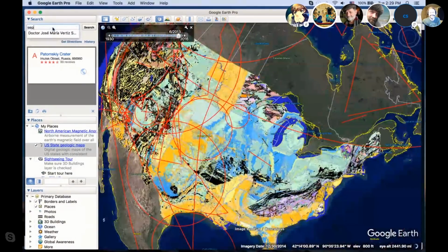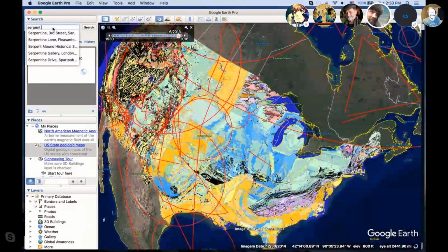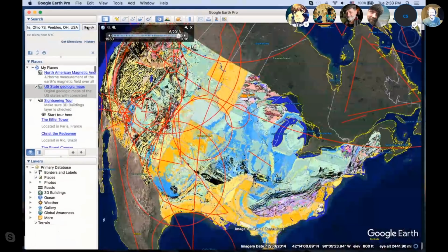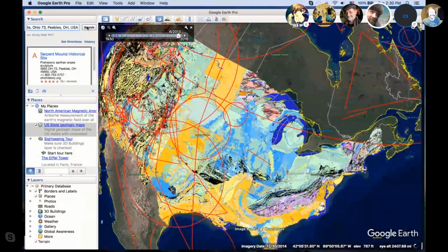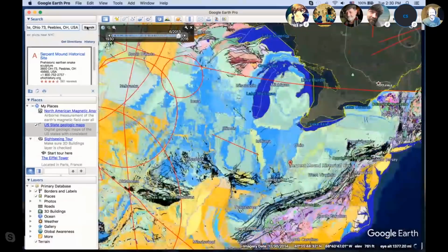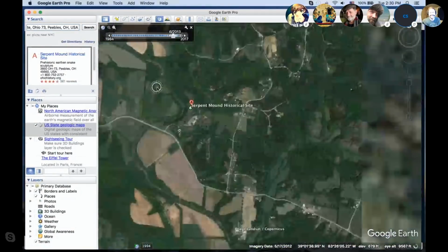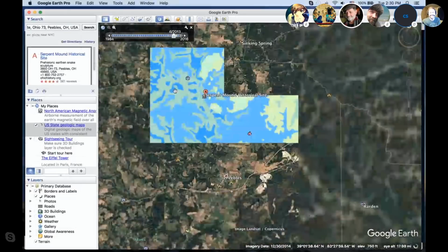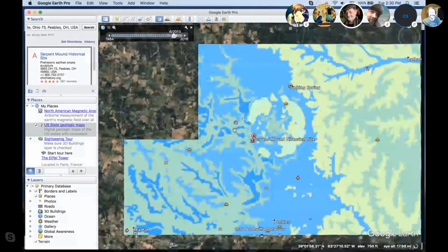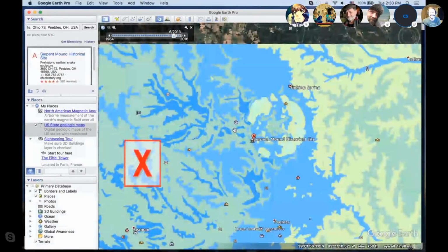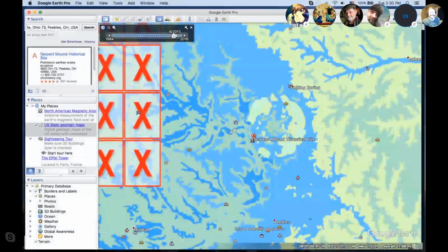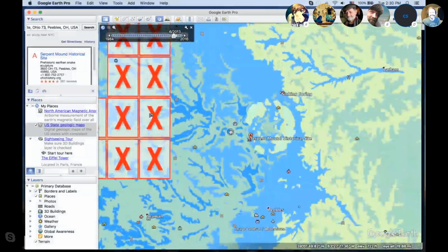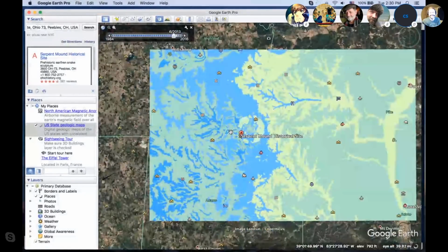There's actually a chart. You can pick it up on Wikipedia and stuff like that. Basically, it's designed to show you how far away you can get from something that is striking the ground, depending on the lethal radius, so to speak, because the amount of current hitting an area causes voltage spikes. Now, obviously, the ground does conduct current, but it doesn't conduct it instantly. There's a resistance.